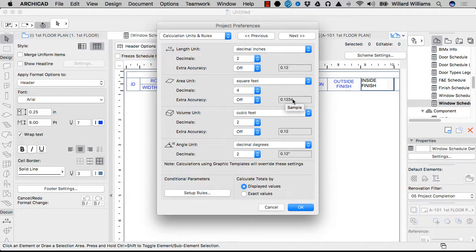It took me a long time to locate it, but it was here that was causing it. It was because I created the schedule with this accuracy turned on. So I actually had to remake a duplicate schedule with this information turned back down. So we'll just set that back.